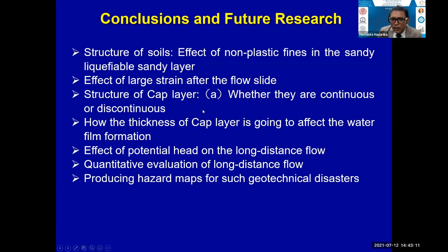Then the structure of the clay layer, whether it is continuous or discontinuous, and the thickness of the cap layer, how thick it is, and the effect of the potential head on the long distance flow, because that head is going to affect the long distance flow of the area. And we have to quantitatively evaluate such a long distance flow either through numerical simulation or through model